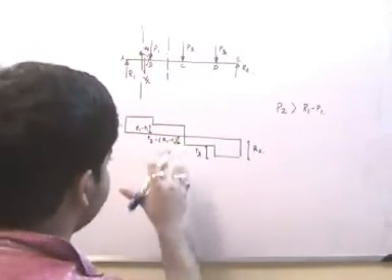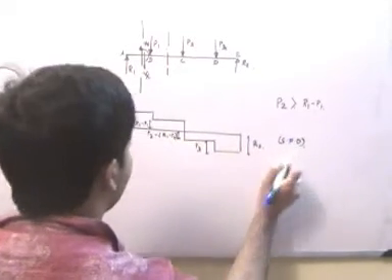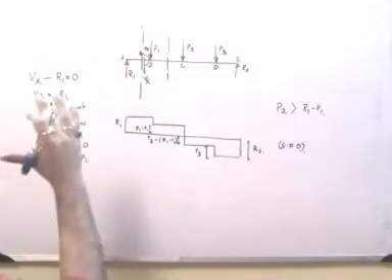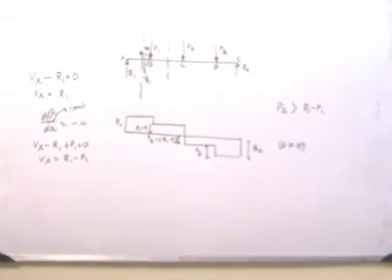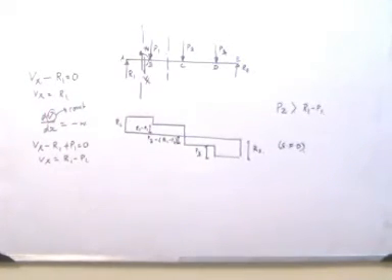So this is the shear force diagram, and from it we can make one or two observations. The first observation is that in a region defined by two points, if no transverse concentrated loads are acting, then we have a constant value of shear force, because W, the intensity of load, will be 0, and therefore V will be constant.